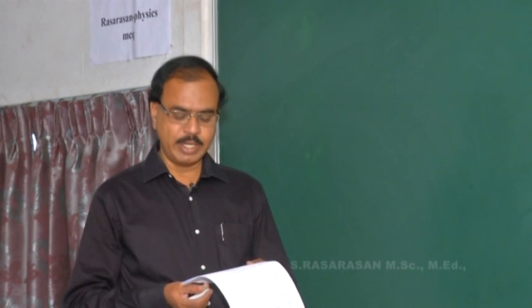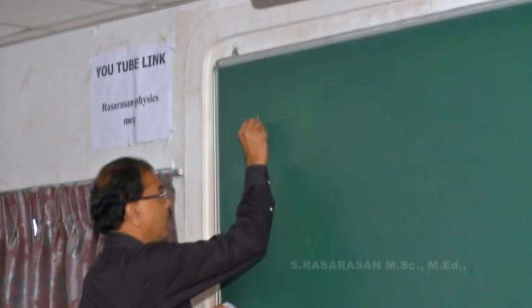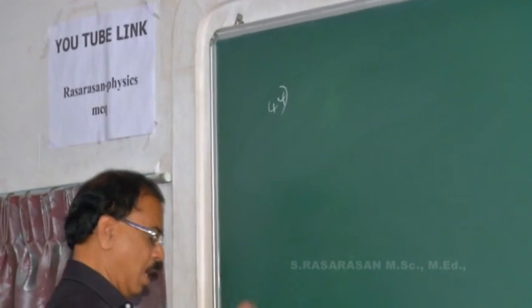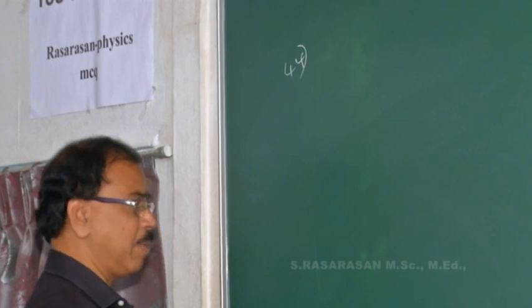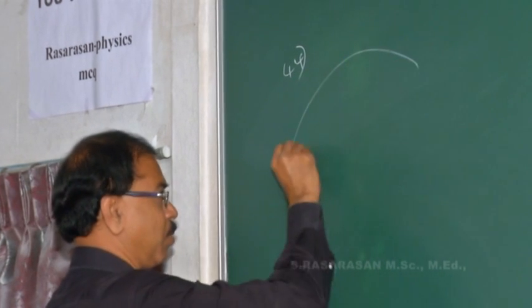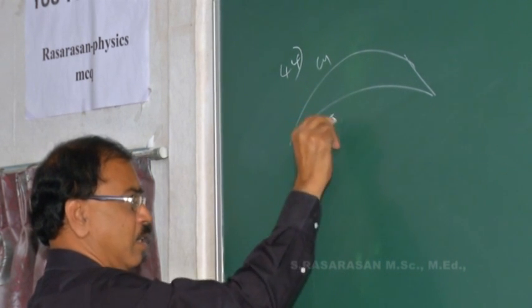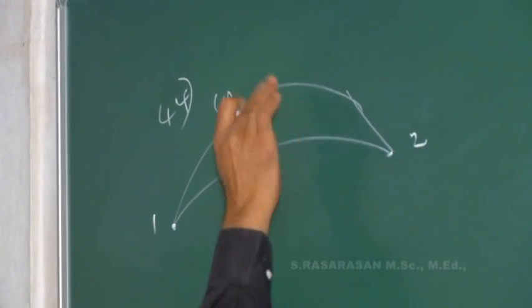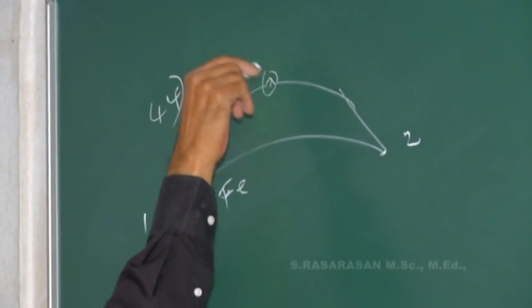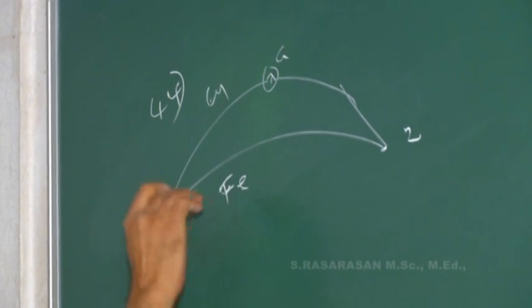That is, in a thermocouple, the temperature of the cold junction is minus 30 degrees Celsius and the neutral temperature is 270 degrees Celsius. Say this is the thermocouple, say this is copper and this is iron, two dissimilar metals connected to form junction 1, junction 2. Here some galvanometer is connected, EMF is produced, current flows, showing deflection.